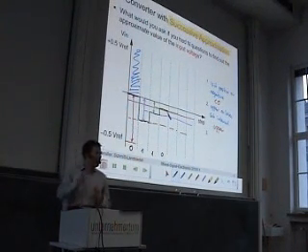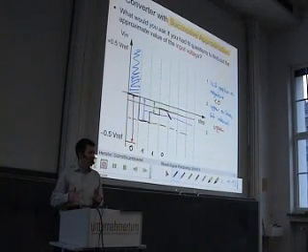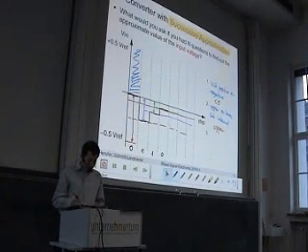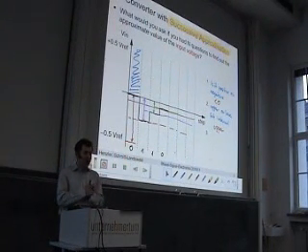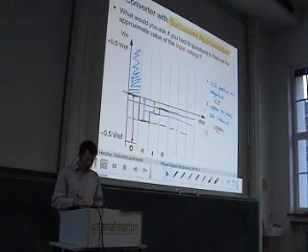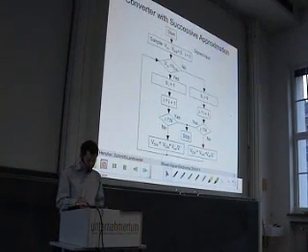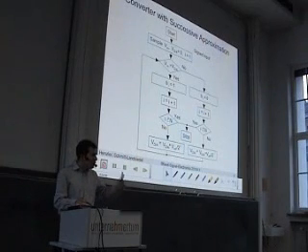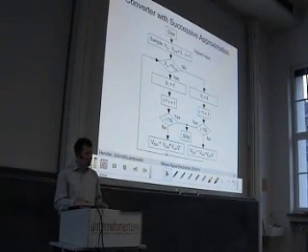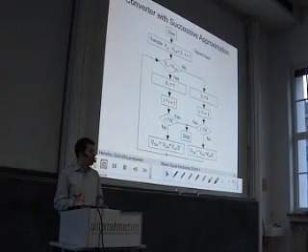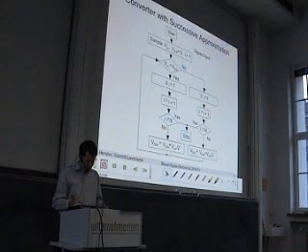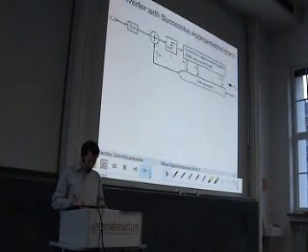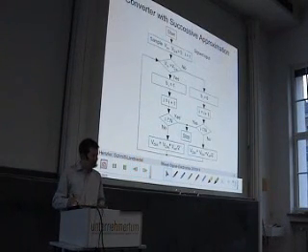And what you can see, the more steps that we perform, the more this internal voltage converges to the sample of the input voltage. So we have an internal voltage, VDA, and the more steps we have, the more equal the VDA is to the input signal, V in. And after a certain number of steps, which corresponds to the number of bits of this A to D converter, we stop the algorithm and then we are finished.